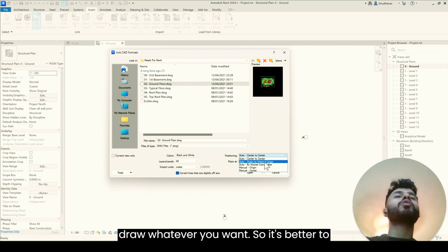And I always recommend to start with a floor that is common among all the floor plans. And you develop that floor, then you copy it throughout the entire buildings. Then you can work on the extra. That can save you a lot of time.